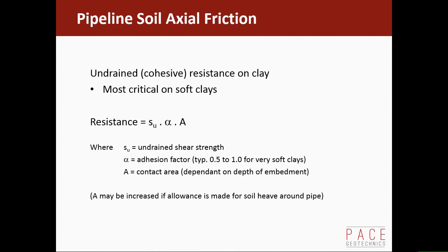And it may increase. You remember I showed berms around the pipeline, so if you have that sort of effect, then your contact length may increase like that. So you may get a higher axial resistance than you expect.